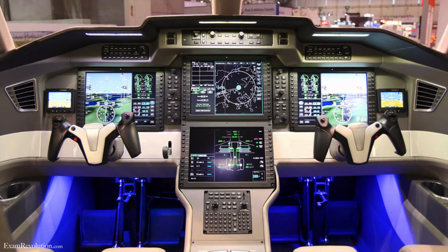Now, you will see that once again, this changes from aircraft type to aircraft type. Sometimes they just give this top part with the airspeed and the attitude of the aircraft and the altimeter and the VSI. Sometimes they give that as one screen, and then the HSI is a screen by itself, right? So it can be split into 2. So the little bit older systems have got them split into 2, but as the aircraft becomes newer and newer, then they actually integrate them both into one PFD.